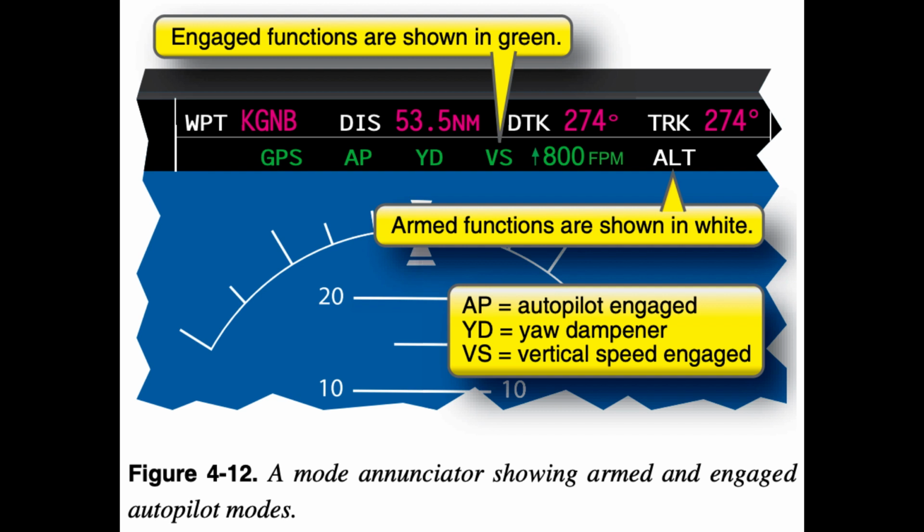Common errors occur when setting 10,000 feet versus 11,000 feet. Too many ones and zeros can confuse a fatigued, busy pilot, resulting in setting an incorrect altitude. Awareness, automatic mode changes.